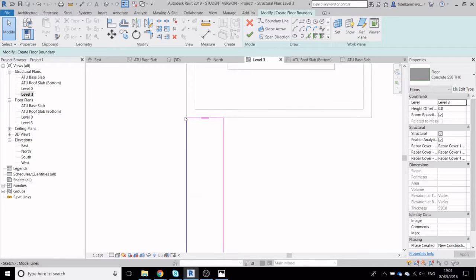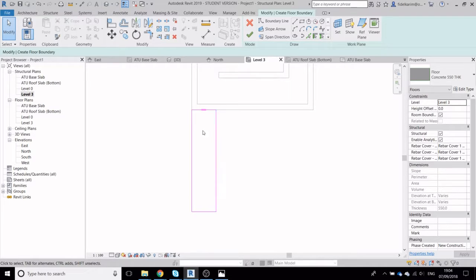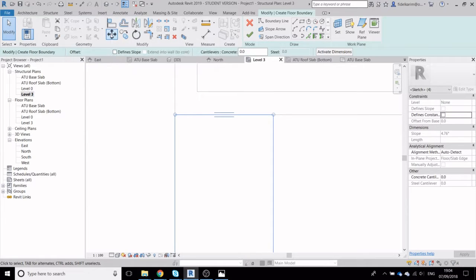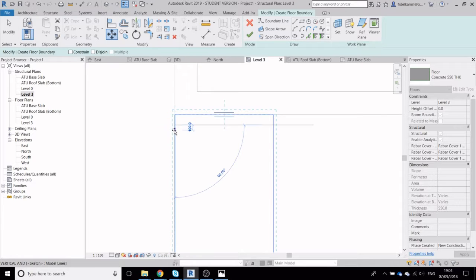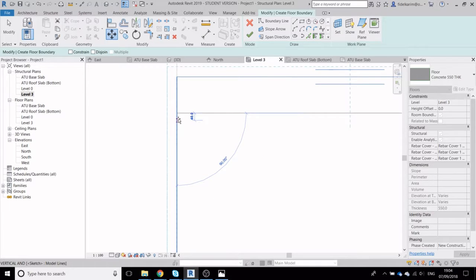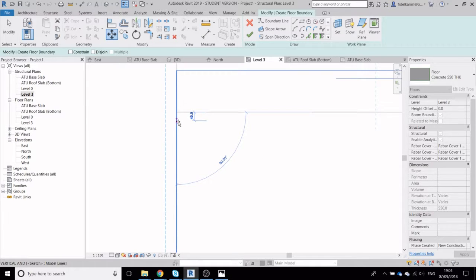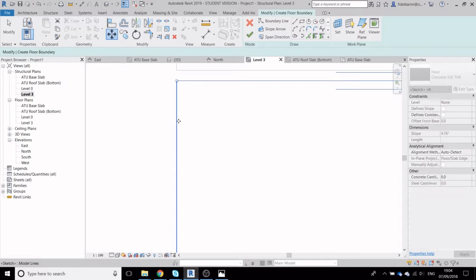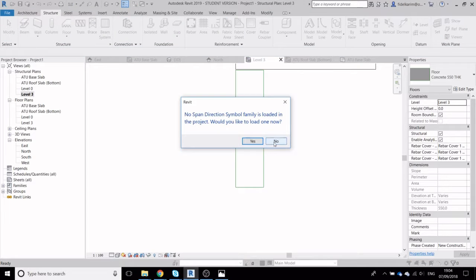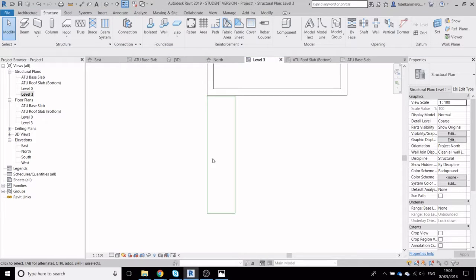And now I want it to be 50 millimeters away from the edge because I want to put some kind of board material in between. So select any base point, zoom right in and say, well, I could just type 50. Yeah, and that's it. No, I don't want that thing.